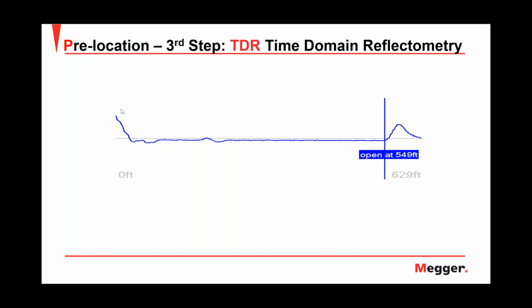This is the change of impedance that we have at the beginning of the trace. The second change of impedance that we can see very clearly is the end, in this case, the end of the cable. But if I have, let's say, a pinhole fault, it will not be possible to see that fault with the low voltage trace. So what I need to use is the arc reflection method, the next method I would like to talk about.